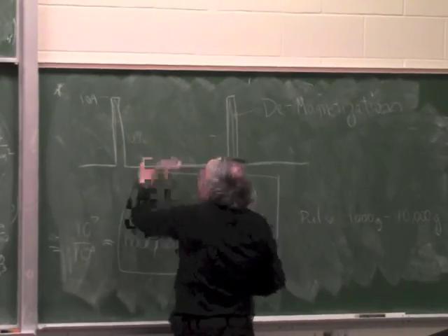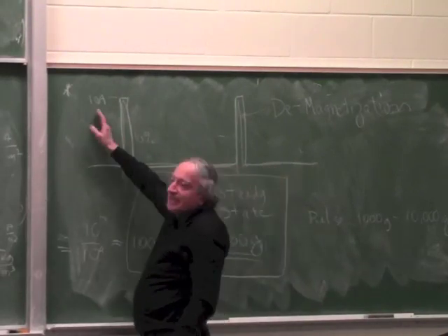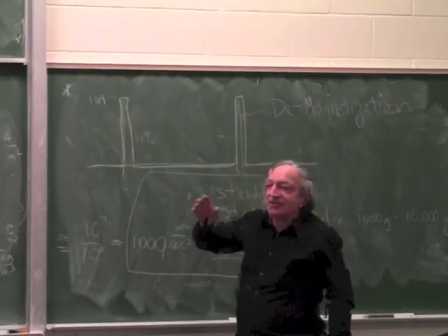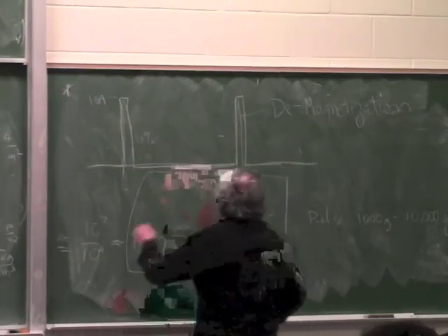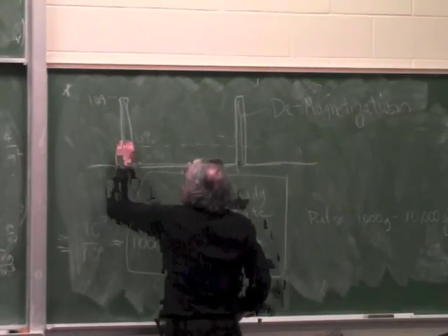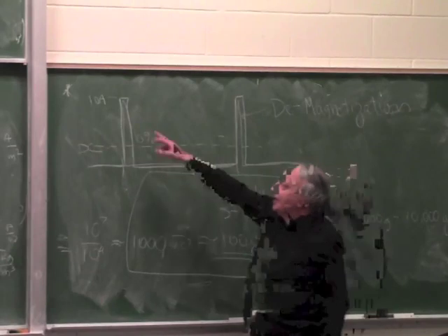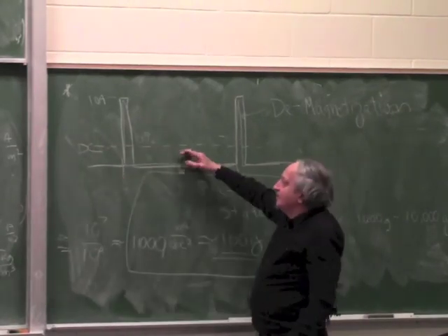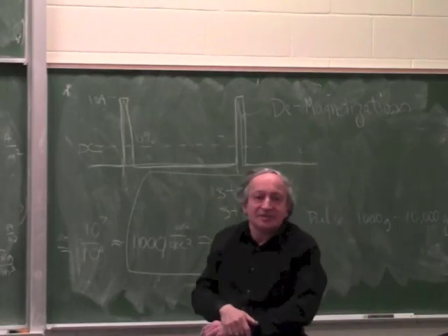So you have 1 second, and during this 1 second, for a tenth of a second, you have 10 amp. I want to calculate to what DC current this is equivalent, because the heating is derived by an equivalent DC current. So if I want to convert this 10 amp for 10% of the time to DC current, what would be the DC current which will replace it in terms of heating?